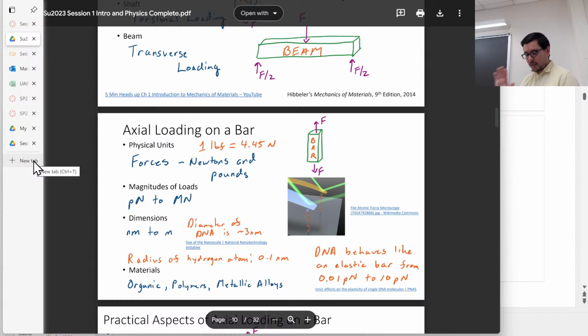So silicone changed my life when I was a graduate student. I focused on how to get rid of bubbles from silicone. That was my PhD thesis. What we did is we spun the liquid before it was curing, or as it was curing, and the bubbles would travel as you spin a liquid. We would introduce hundreds of Gs essentially to the liquid. And we did some at Rutgers as well. But when you do that, you're spinning a disc, for example, that has liquid in it.